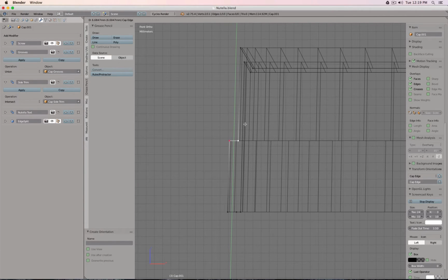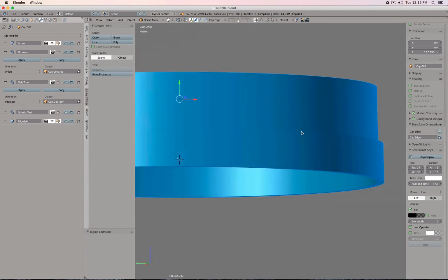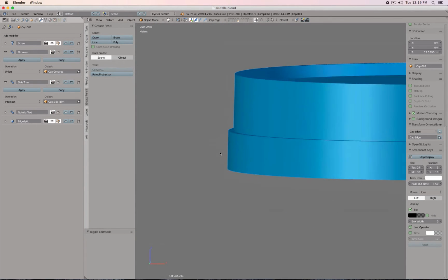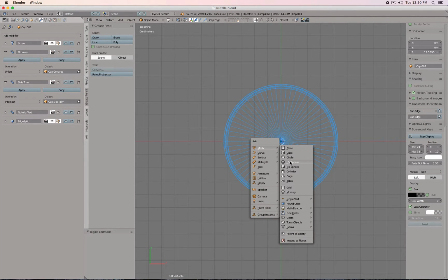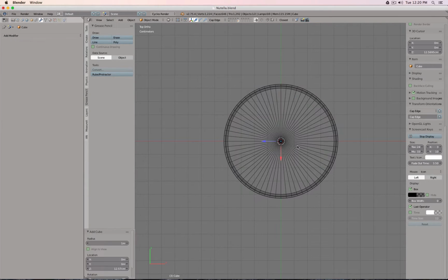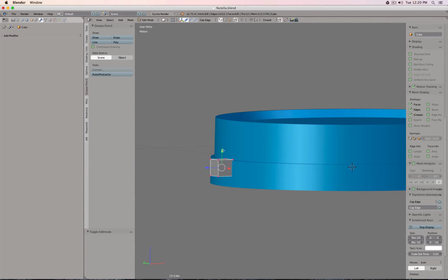So this is one of the other fantastic modeling parts of Blender, that you can easily create those custom vectors and then use them for all translation commands. Okay, so now I changed the height, and let's say I would like to cut elements out. I could also say, well, here is a small cube. I'm going to make it simple and fast for the computer to calculate. Then I move this one out. You see I created the object at the world center, and then I move the mesh out. Very important to follow that step.